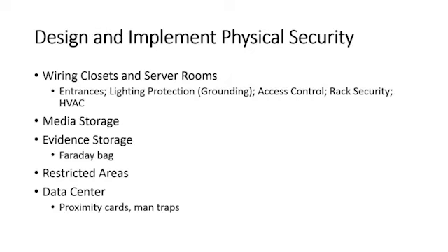Got to think about HVAC a little bit too, our heating and air. We don't want our server rooms and our wiring closets, our comm closets, getting too hot. Heat is not good for servers. Heat is not good for our electrical equipment. On the flip side, being too cold in there is not good for them either. We want it kind of cool, right? 60, 65 degrees. Now that might sound a little chilly for a human, but we're not hanging out in there. This is not the break room. But this is a really good idea for your electrical equipment because you do need to keep it somewhat cool, but we don't need icicles hanging off the servers.